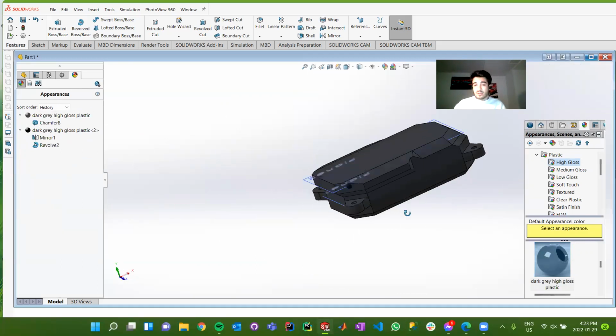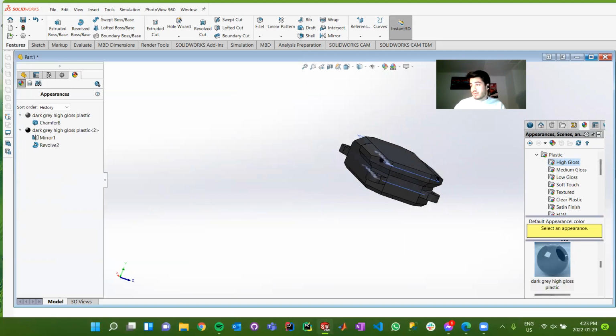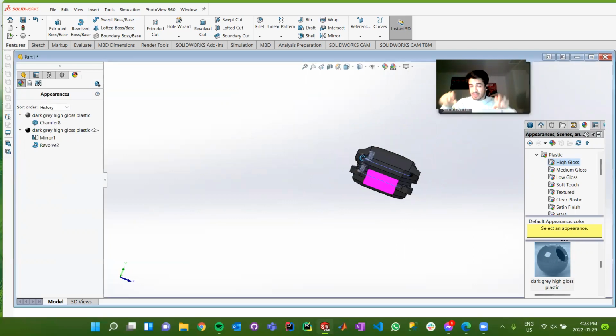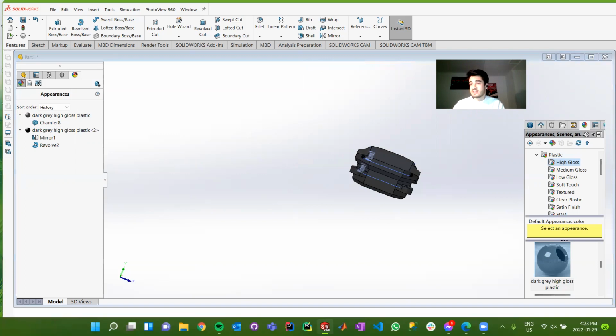That actually wraps up what our chassis sort of looks like. What we could also do is just reduce the size of the chamfer underneath, which is actually what I'm going to do. Because as you can see, this chamfer right here makes putting the actual arm assembly in a bit too tight. You'll see what I mean when the next tutorial comes up, but at the moment, that isn't a lot of clearance to deal with. So I'm just going to check to see what I used for my original chamfer dimension. I used 0.5 inches. We can do the same here.